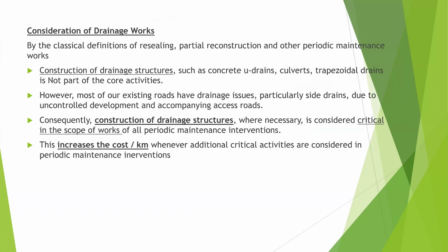Construction of drainage structures such as concrete U-drains, culverts, and trapezoidal drains is not part of the core activities. However, most of our existing roads have drainage issues, particularly side drains, due to uncontrolled development and accompanying access roads. So consequently, construction of drainage structures where necessary is being considered to be part of the scope of works of all our periodic maintenance activities.